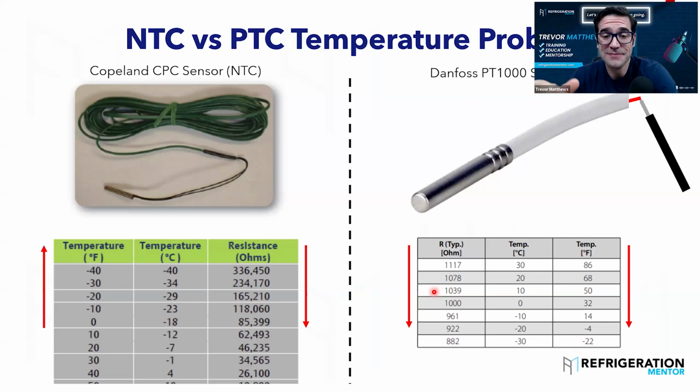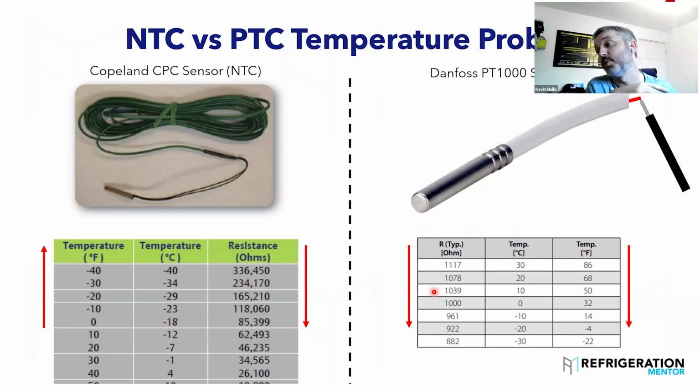Yeah. So, worth saying as well, very, very rarely the input on the controller will go faulty. Now, Danfoss says 180 degrees if the probe's open, but there's nothing to stop you flipping the plugs for the air on and the air off round. Let's say if you think the air off probe's faulty, but you've changed the probe and the reading still looks terrible, plug it in the air on. If it then starts giving you the correct reading and you've got no offset in there, the chances are that controller does have a fault on it.